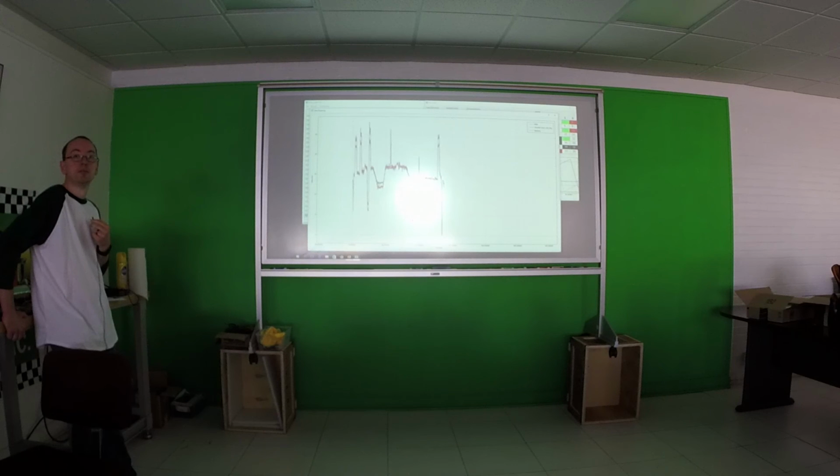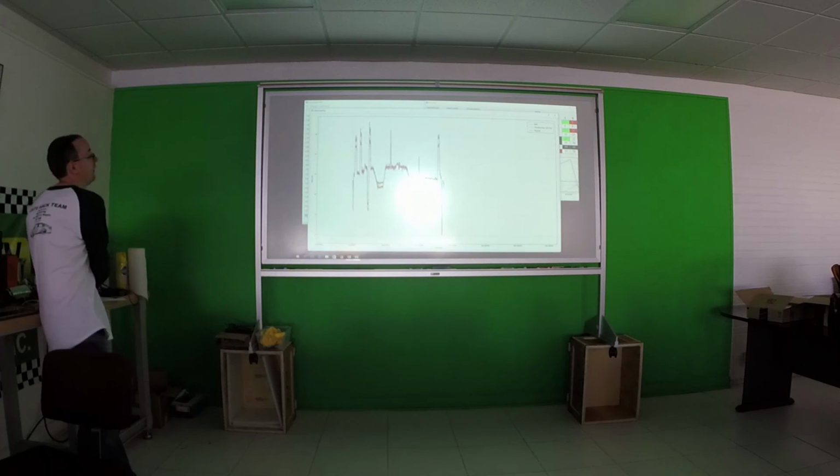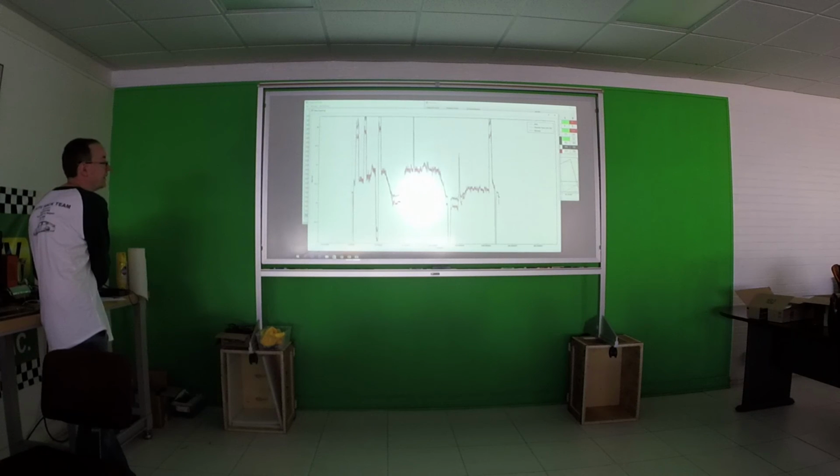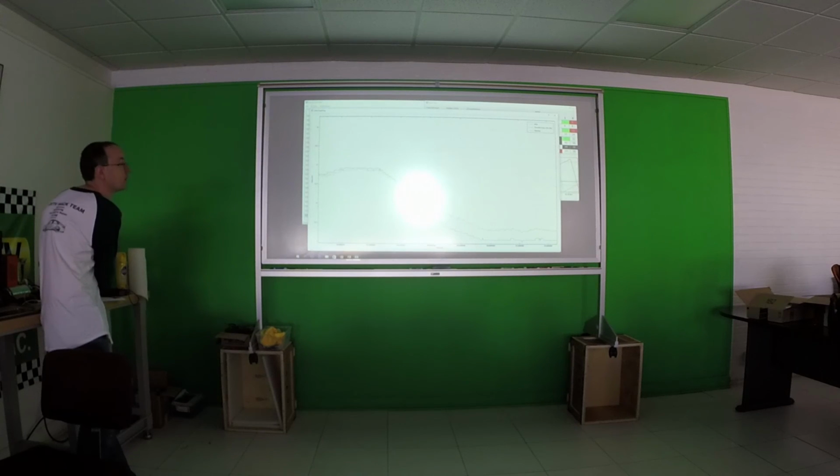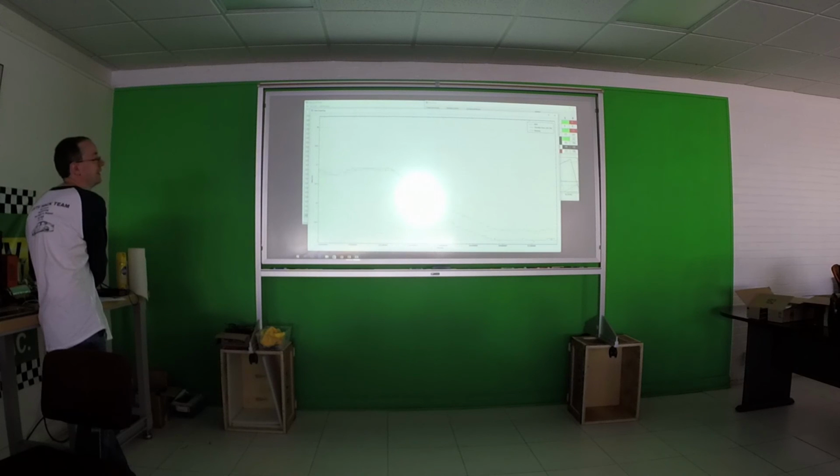There's no time phase shift in those signals? Sometimes you can see it. You can kind of go in here and try. Like with this, if I really zoom in, that's the usefulness of being able to zoom in on one axis. It looks kind of like the red one is responding first, but not by a lot. And because it's blockier, sometimes it's still hard to tell who's following who. But zoomed way in, you can look. It would be my theory that the red one is the master because it seems to respond just a fraction before the other copy. If you were to look at the two individual CAN messages, if you were to see a large change.